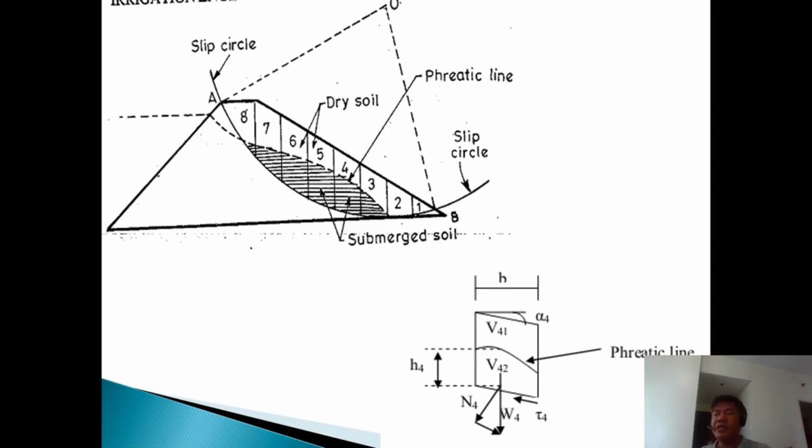In my experience, in the preparation of my calculation report, I present them in separate analyses: one analyzed in terms of slope stability and one analyzing only the seepage. But in the software, because you can clone, you will not be doing another model.